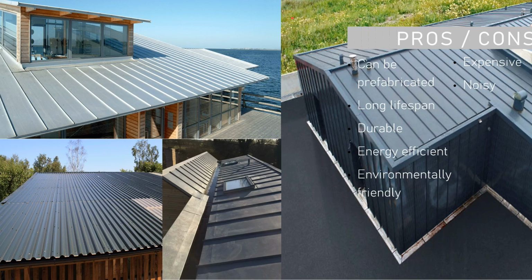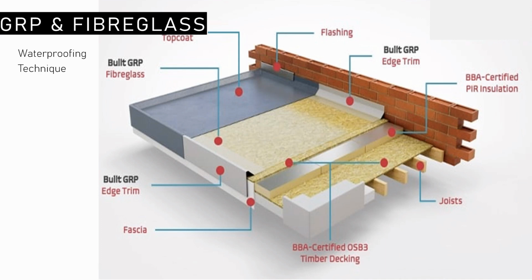Despite the benefits of the metal roofing system, it can be expensive, with just 1 square metre ranging from £10 to £100. The installation labour can also be expensive due to specialist training, knowledge and equipment required. Additionally, the metal roof can be noisy and project the sound of hard rain and hail throughout the building. This will be a disadvantage for Quayside Tower due to the commercial requirements, such as the conference rooms on the top floor.